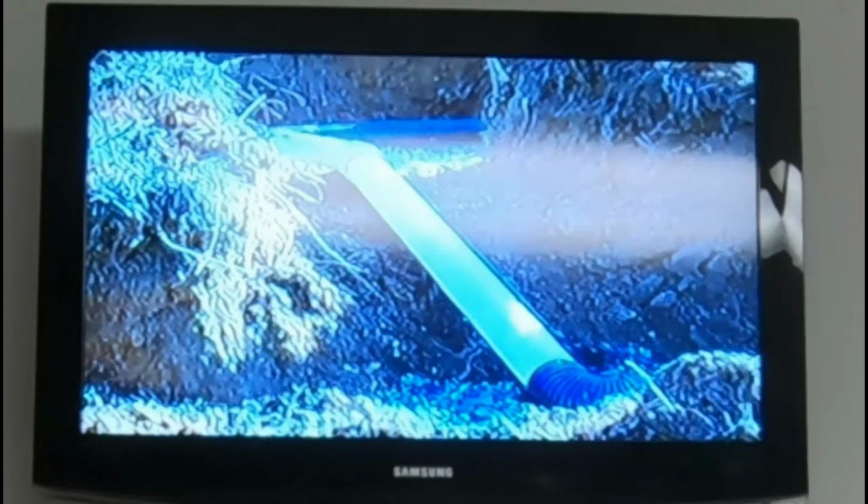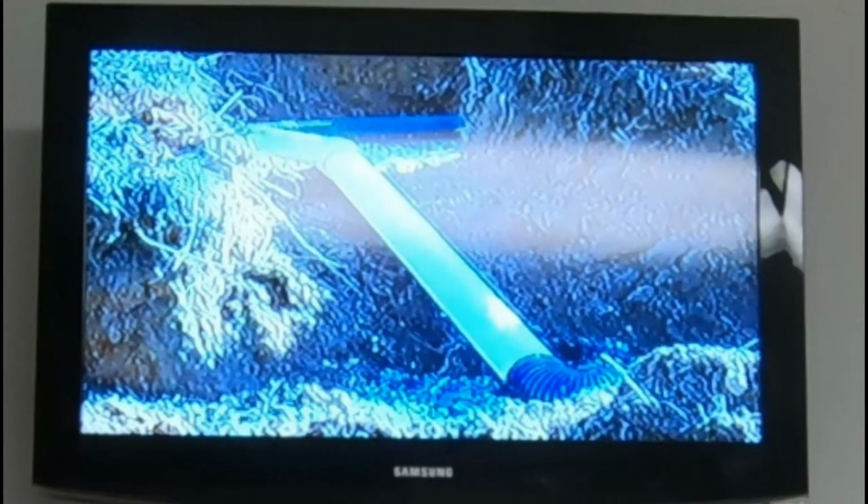It's important for the contractor to ensure that the ditches, the elevation of the spillover is not above the outlet of the tank. You must have at least 4 inches difference between the top of the spillover and the outlet of the septic tank to ensure that the water cannot back up into the system prior to overflowing to the second ditch.